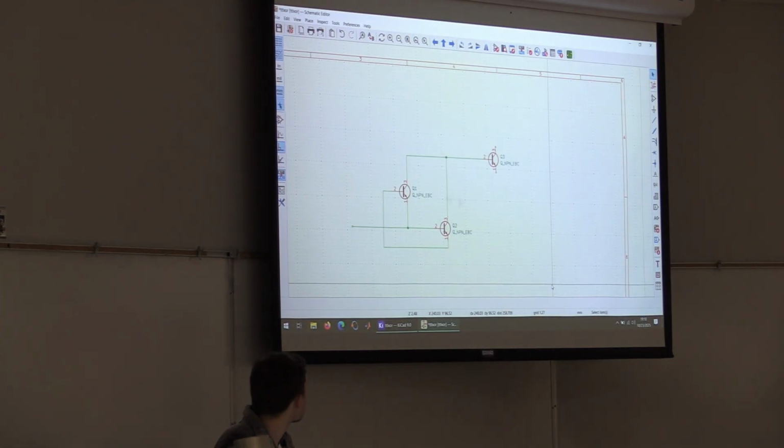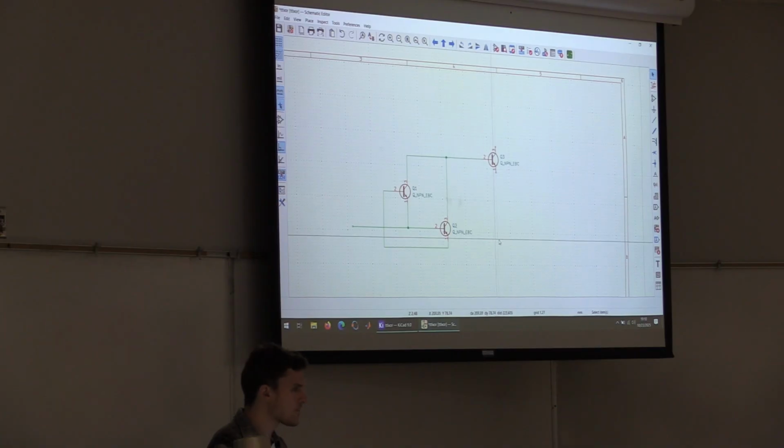Now, as you guys are drawing that, just to go over some basic symbol drawing patterns you'll see. In some schematics, you might see wires going over other wires with like a little arch. Typically, that's not done in industry anymore. Instead, we use dots. And then where we don't have a connection, we have just a crossover line, sort of like that.